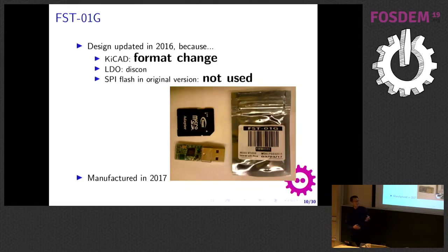But anyway, I understand it was required. And some chip, an LDO, was discontinued. So at that time, I needed to update my design. And I found that the SPI flash in the original version of FST01 was not used by anybody. So I removed the SPI flash from the board. It was designed in 2016, and it was manufactured in 2017.